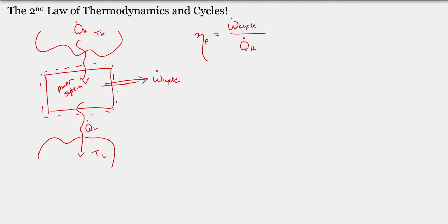Okay, the second law of thermodynamics tells us that there is a maximum performance associated with a heat engine. Okay, so that maximum cycle efficiency is defined as the Carnot cycle efficiency. So that's η_P max, or if you prefer, that's η Carnot. And if we look at this definition here, this is the easiest way for us to memorize these formulae, and you should know them. If you're working in this area, you should know them from memory because they're that important.